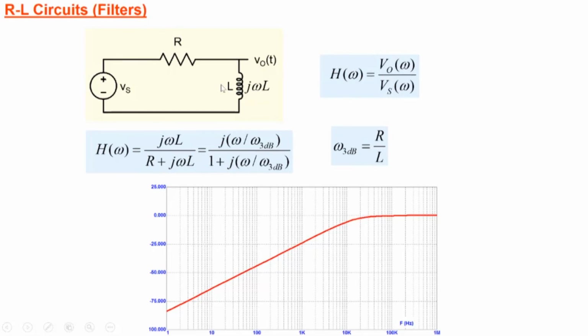Well, let's look at it at low frequencies. What will it do? The two asymptotes that we talked about, low frequency behavior and high frequency behavior. So at very low frequencies, this will be a short, and therefore V0 is 0. While at high frequencies, this impedance is going to be very high, almost going towards infinity, and therefore all the voltage will appear across this. So at high frequencies V0 will be Vs, and at low frequencies V0 will be practically 0. So it's a high pass filter.